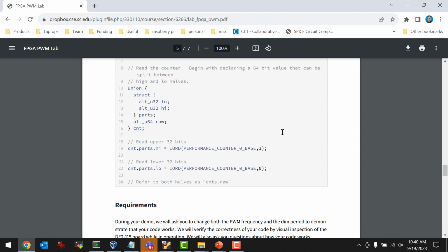And then all I have to do is write it through 32 bits, but then when I read it, I can read it as the 64-bit value. That's the point of this, right? I need to be able to write it as 2 32-bit values, but when I use it, I have to use it as a 64-bit number. Does it make sense? So I write it through high and low, and I read it through raw, right? I don't know how else to do it because, like I said, we used to just have a raw value and just shift high by 32 bits and OR it with low, and we were done. But then, like I said, GCC lost the ability to do that.